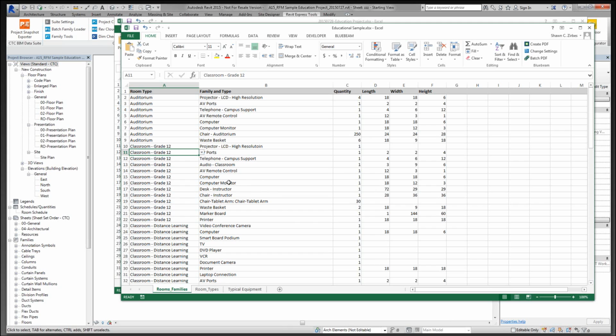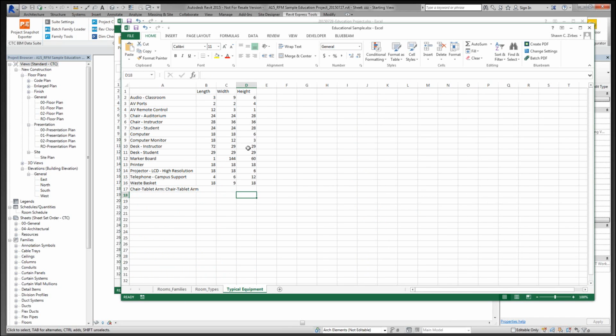Now, I'm going through and specifically using the lookup here because in previous workflows, I've noticed that if I entered a computer, for example, and I didn't have the same width, length, and height, then as it placed the next computer, it would automatically reassign the width, length, and height, and I might get some oddball results if I don't carefully manage my actual physical sizes. That's why I decided that a lookup might be really nice, where these three columns here are doing a lookup based on the value of this cell right here and pulling its length, width, and height off of this extra tab.